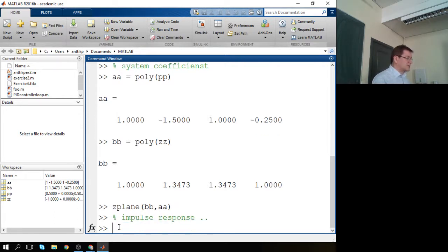And for the impulse response, we need an impulse. And for the impulse, we need some indexes, for example a vector that starts from the negative side and then goes somewhere to the positive side. In this, you need at least the order number plus 1 points. At least.